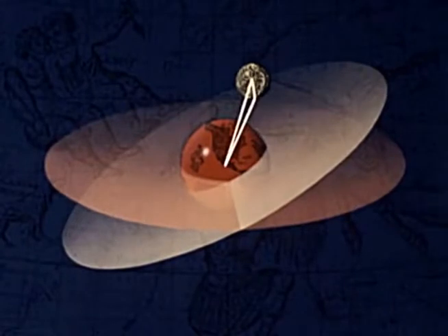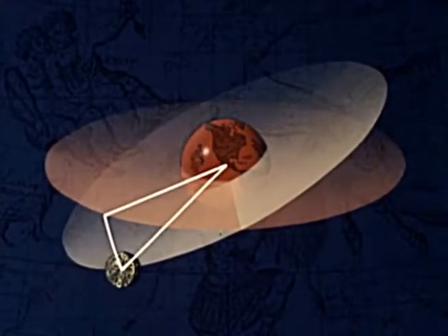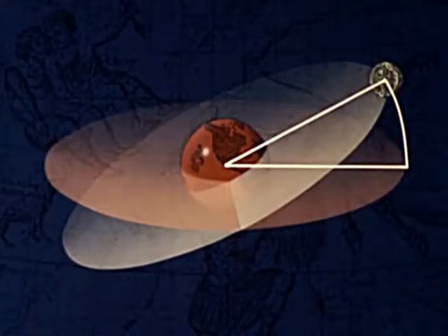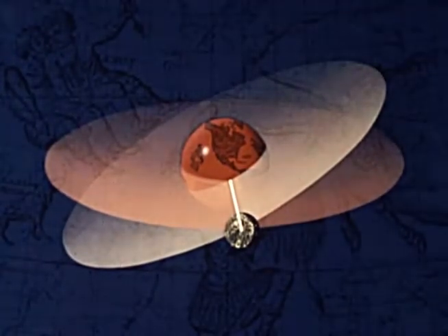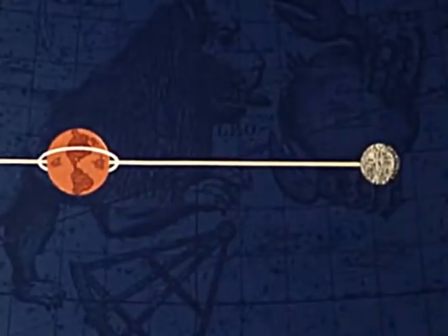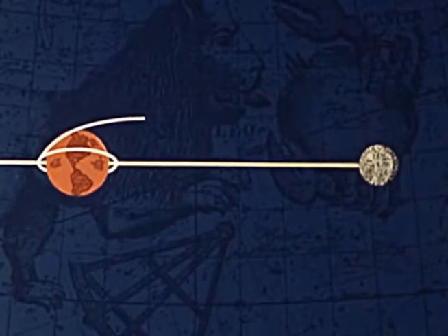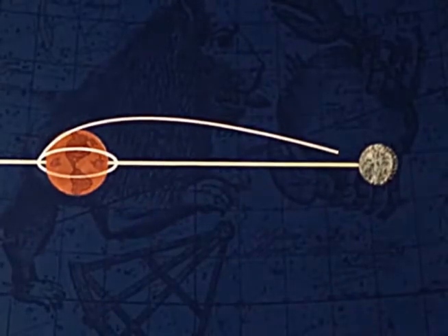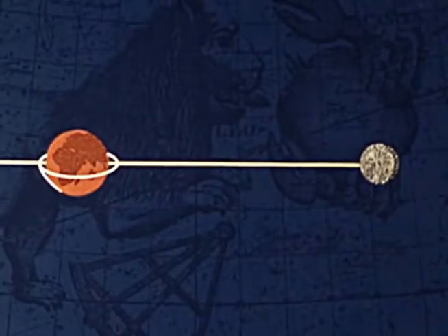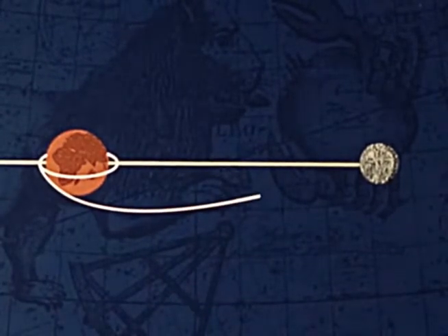The angle between the equatorial plane and the Earth-Moon line is called the angle of declination. This angle varies from about 28 degrees when the moon is here to 0 degrees when the moon is here. Since the spacecraft is traveling to the northeast when translunar injection occurs over the Pacific, a Pacific injection will place the spacecraft north of or above the moon orbit plane. An Atlantic injection with the spacecraft moving southeast will put the spacecraft south of or below the moon orbit plane.